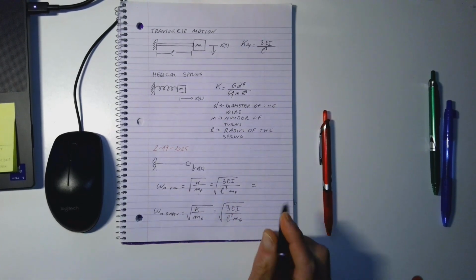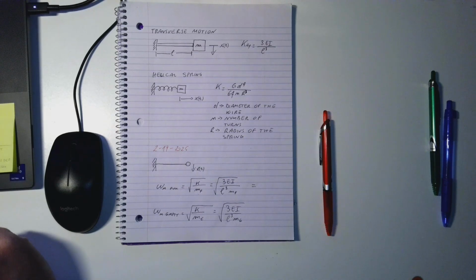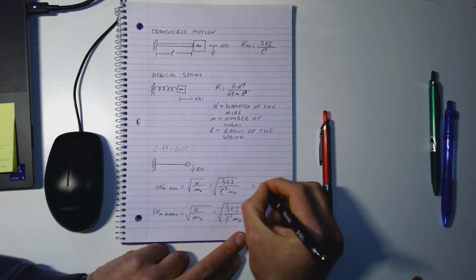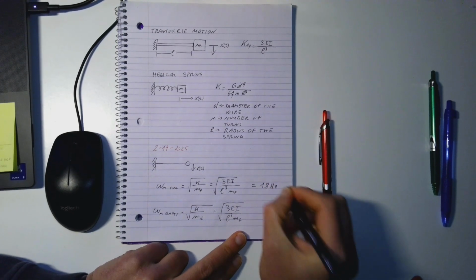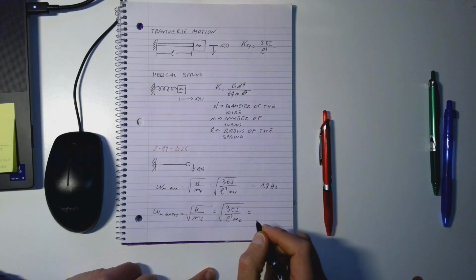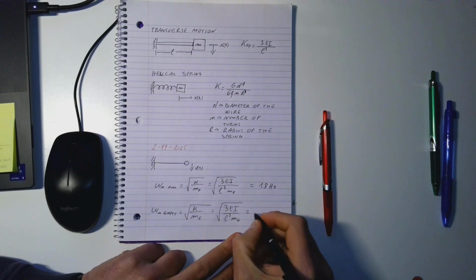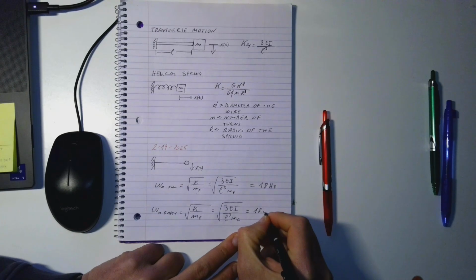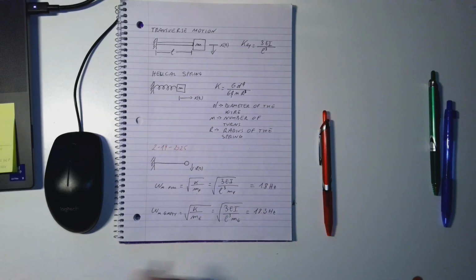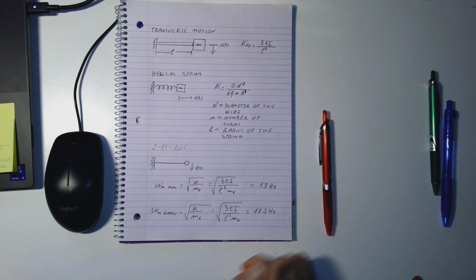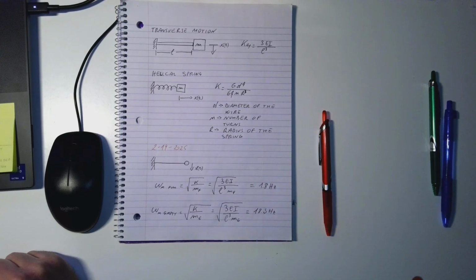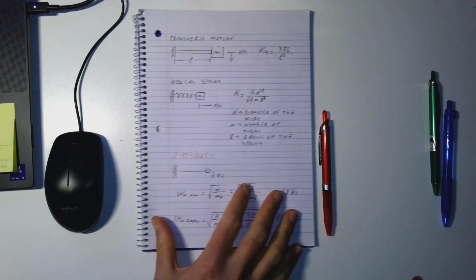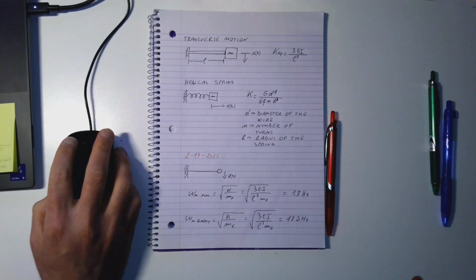When we plug the numbers, we obtain that with the full tank, the frequency is 1.8 Hertz, and then with the empty tank the frequency is 18.5 Hertz. So this is how the natural frequency changes with the mass of the tank. Make sense? This was pretty straightforward. We can quickly look actually at another problem.